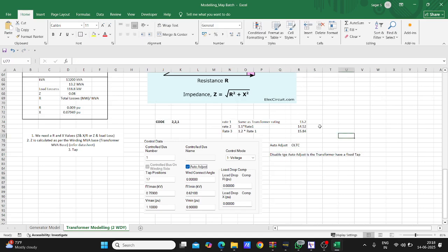Okay, good. So then we need to calculate the V maximum and V minimum. V maximum is equal to, and how can I calculate it? V minimum is equal to. Suppose you have a step size; I have transformer data for the next three-winding transformer, and at that time I will tell you how we can give it. Let us consider your step size is equal to 1.25 percentage. That means your V maximum is equal to 1 plus this value.